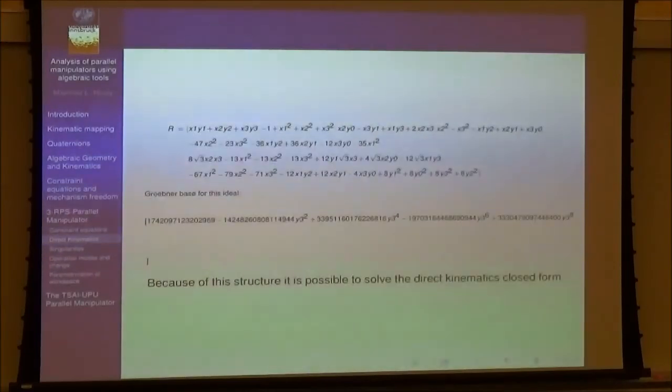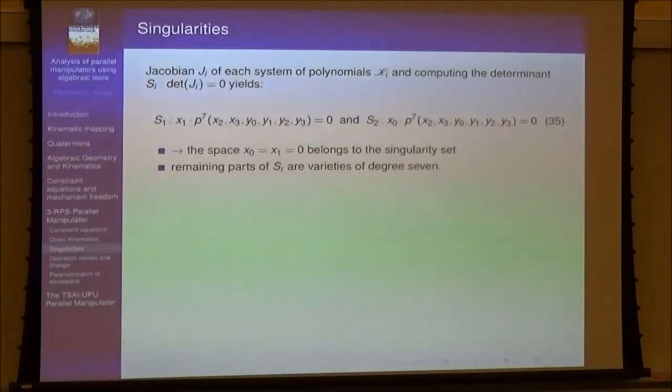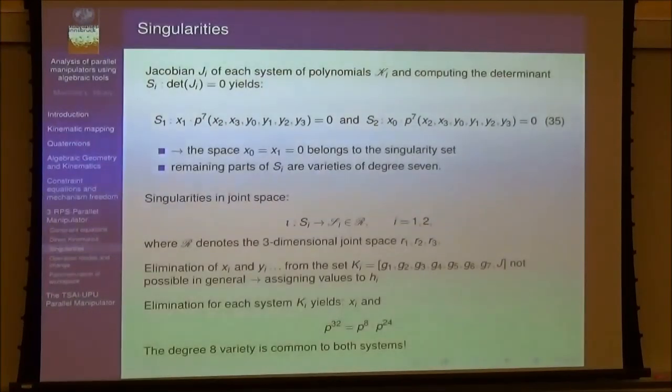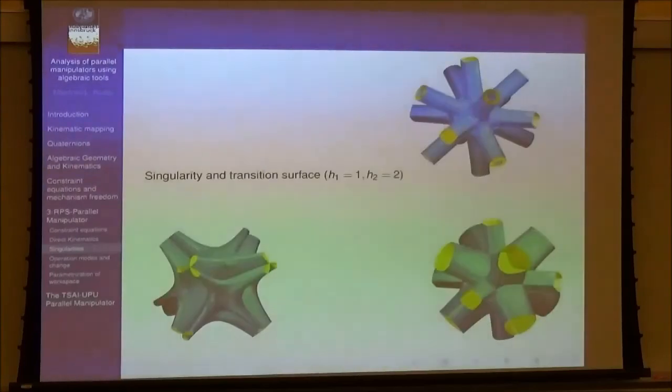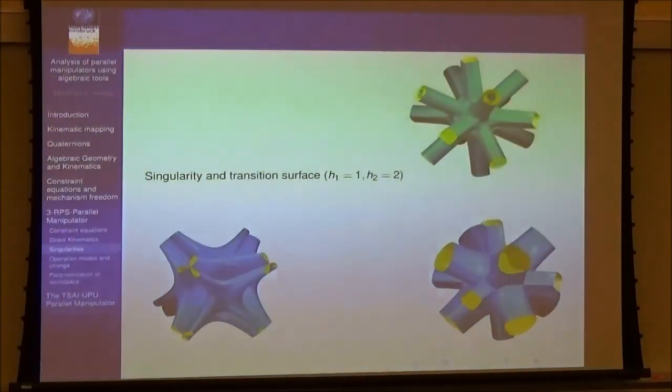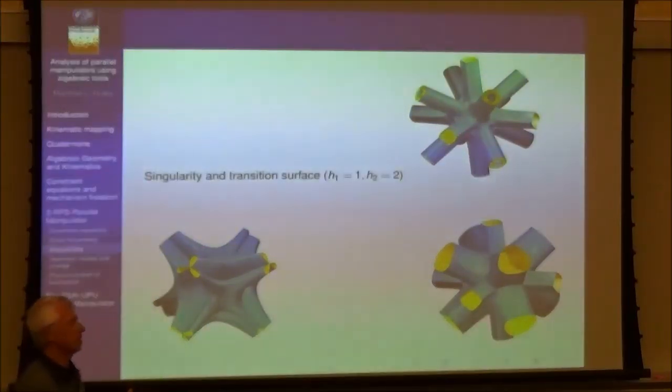Okay, and then you will see in this case you can solve the direct kinematics even in closed form, and can do a singularity analysis, and I will finish with a nice picture. This is the set of all singularities of this manipulator for a special design, and most of the time you will find some very, very nice algebraic objects for the singularity sets.